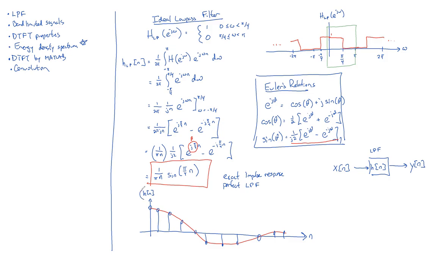This down here is our h of n, and what's in the upper right is, if we move this over, DTFT, into the frequency domain, this would be our input in the frequency domain. This would be our system transfer function, our DTFT, in the frequency domain. And what we would get out would be just the product of our input with our system transfer function. Does that answer your question for us? Yes, sir. Thank you. Sure.